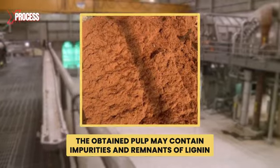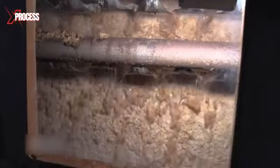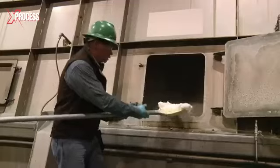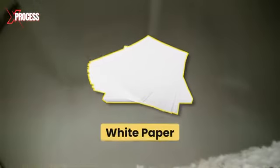The obtained pulp may contain impurities and remnants of lignin. At this stage, an additional cleaning and defibration are performed to separate the cellulose fibers and remove any unwanted material. The fibers are washed to remove the acidic solution, and the pulp is now soft and fibrous. Next, it needs to be bleached before it can be used to make white paper.